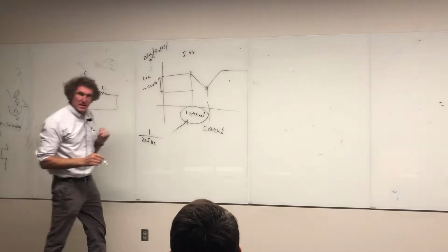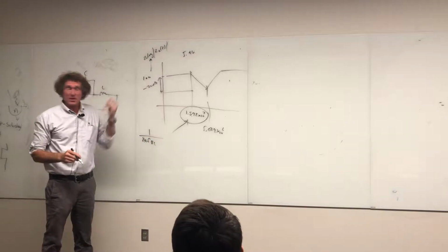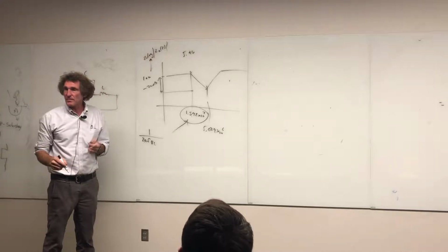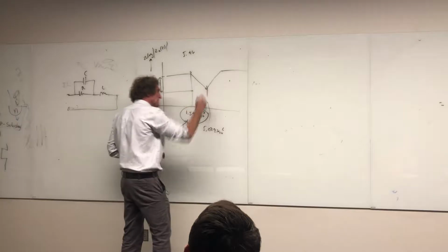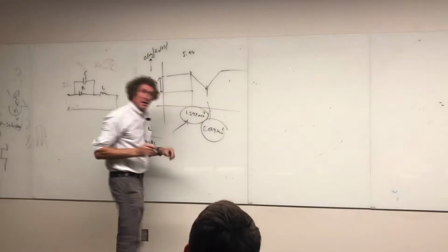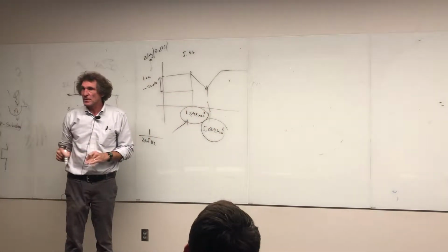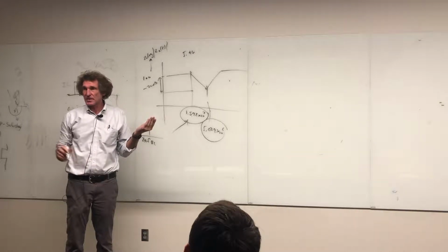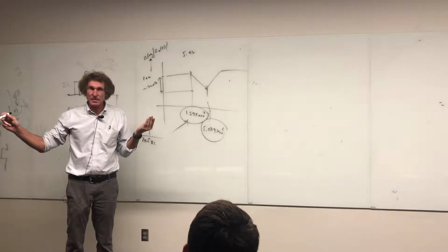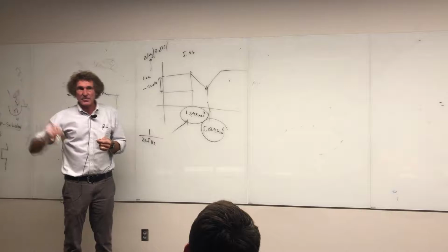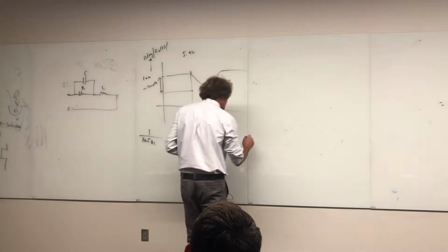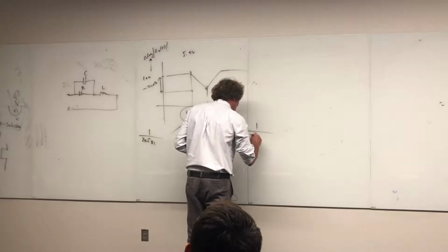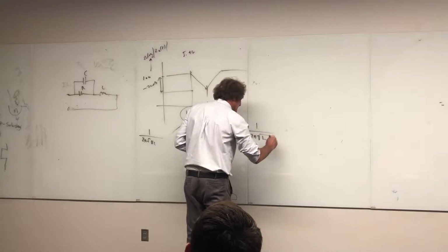Do you remember me talking about this before? You can prove it by writing the impedance equation; you'll see that's where it starts falling. This other frequency is the resonant frequency. Normally omega at resonance is 1 over the square root of LC, but if it's F, you divide by 2 pi: 1 over 2 pi square root of L times C.